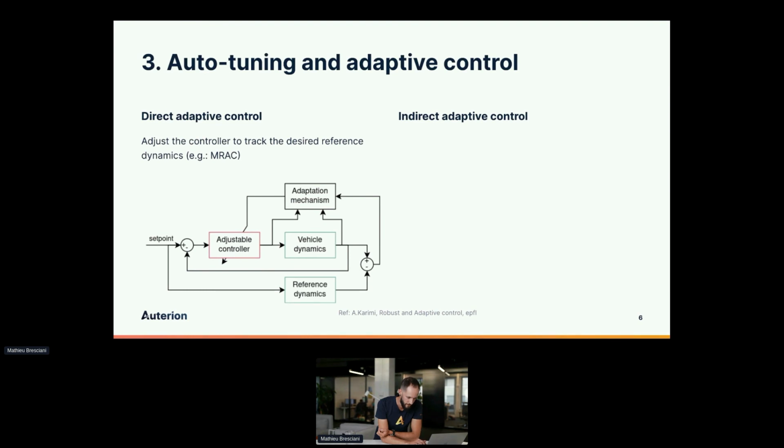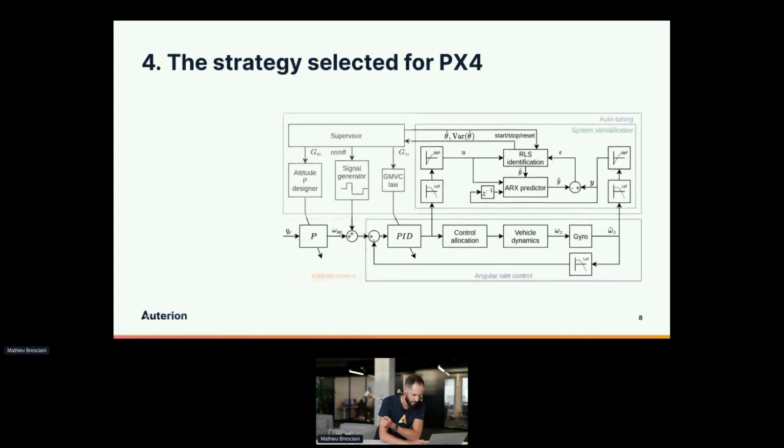How is the closed form computed for the PID controller? Is it based on a pole placement design? It's called GMVC, which stands for Generalized Minimum Variance Control. You have a reference model, and it's an optimization to minimize the variance between the output of the model and what you will get from your closed loop system. It's an optimization that has a closed form solution, especially in our case because we have a fixed set of parameters that match properly. From that GMVC controller, you normally get a polynomial controller, and with some tweaks, we can approximate a PID controller. That's how we can extract those PID gains.